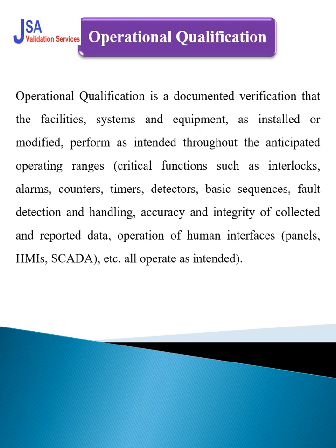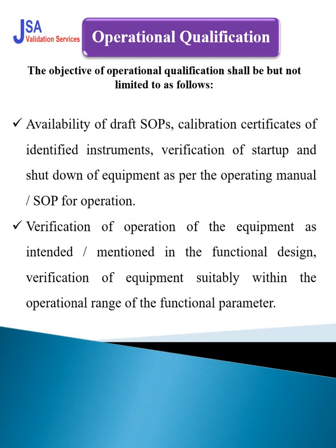The minimum requirements your protocol should contain: availability of draft SOPs, calibration certificates of identified instruments, and verification of the startup and shutdown of the equipment as per the operating manual or SOP. Draft SOPs for cleaning, maintenance and operation should be available.